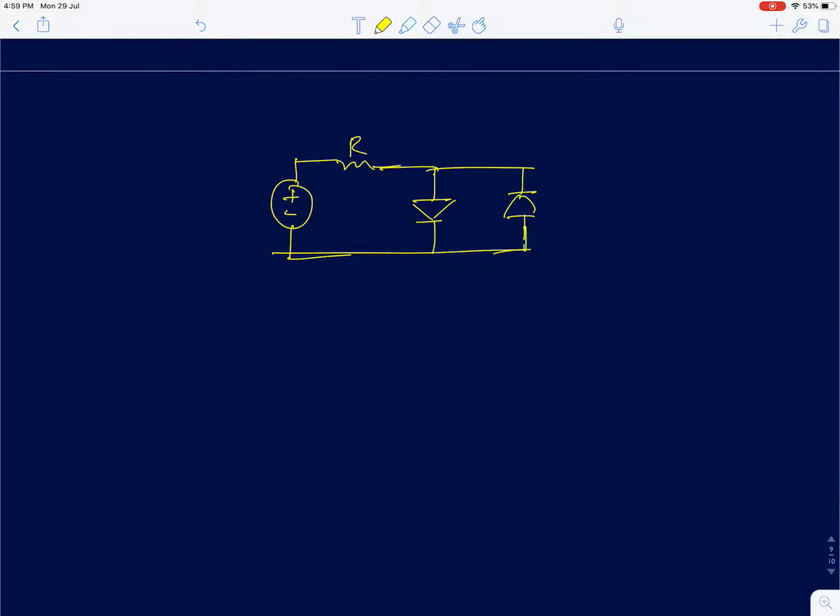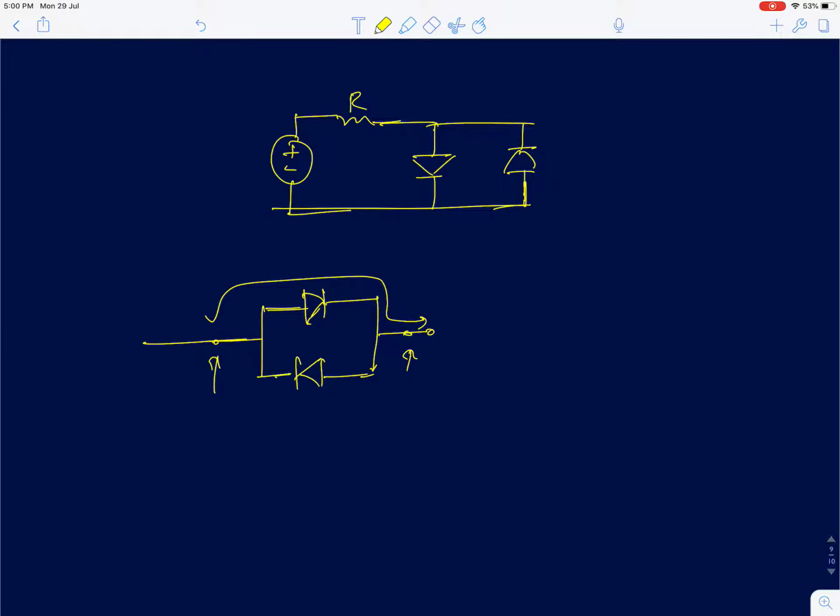I connect two diodes in parallel. So let's just analyze this circuit wherein you connect two diodes in parallel. Okay. Now in this circuit, let's assume I apply a positive voltage across the two terminals. Then what would happen is that this diode will conduct. Assume they are diodes with finite cut-in voltages. So I'm going to call the voltage across it V. If it is greater than V gamma, the above diode is going to conduct.